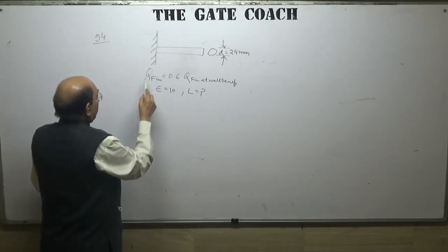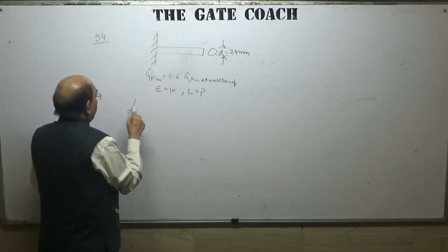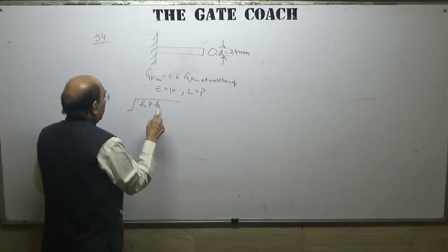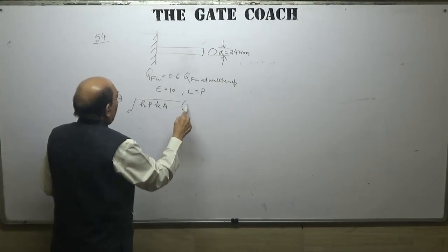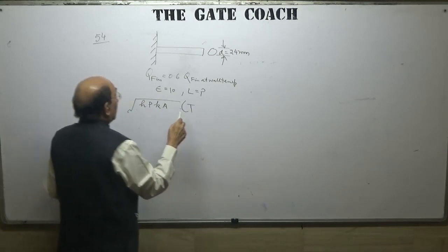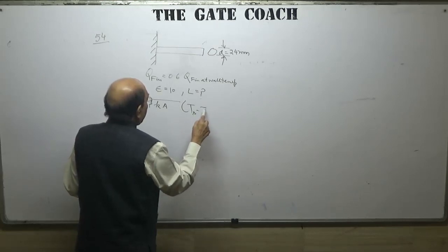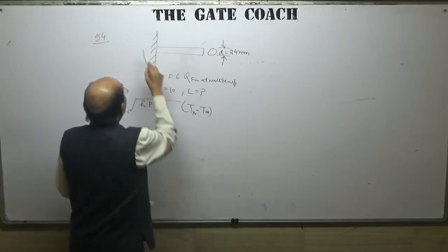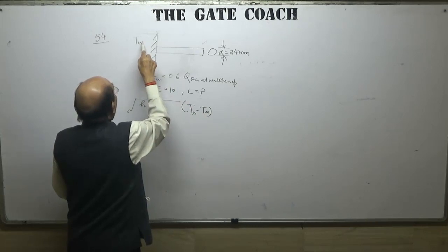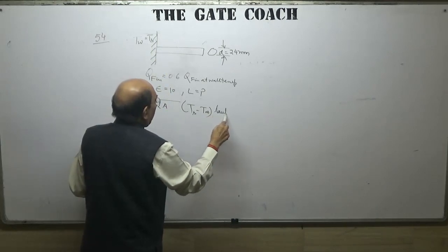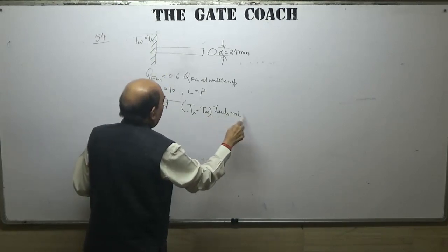Heat transfer from the fin is given by under root of hPkA into Ts minus T infinity into tan hyperbolic mL.